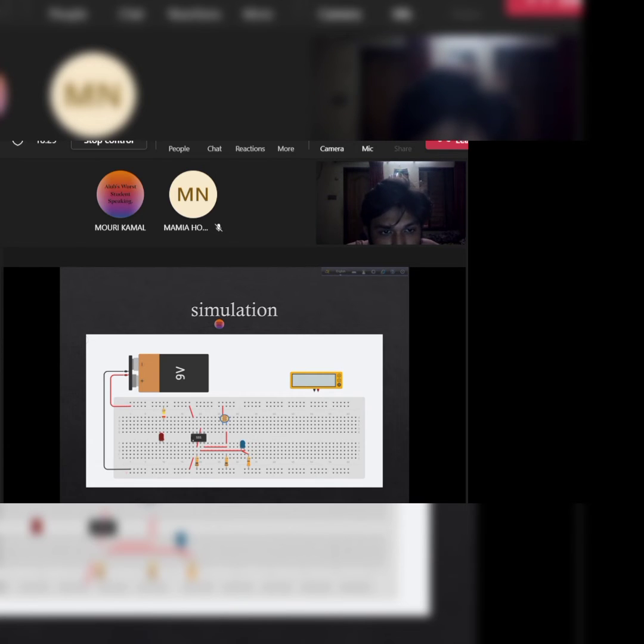So far so good, but how do we make the 555 timer IC understand the change in resistance and take a decision on controlling the output? The only solution is to convert the change in resistance of the LDR to a change in voltage and pass it to the 555 timer IC. This conversion can be done using a voltage divider arrangement. The voltage at the junction of the LDR and the 10 kilo ohm resistor in the voltage divider is passed to the reset pin of the 555 timer IC.